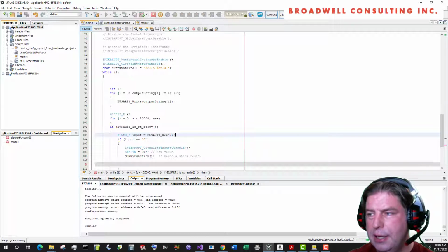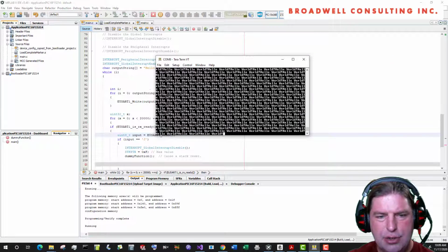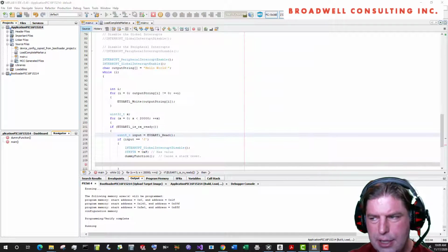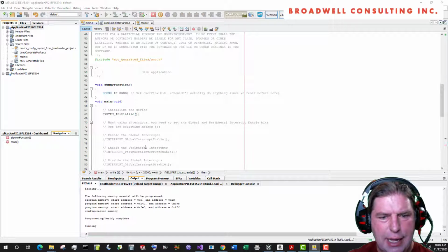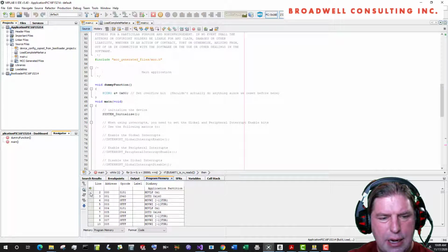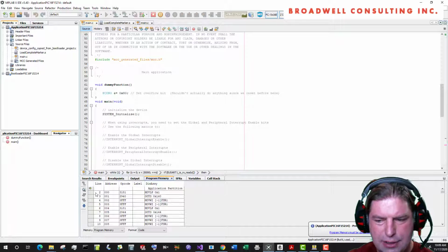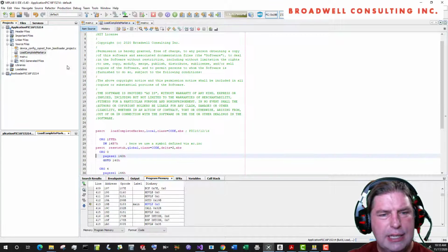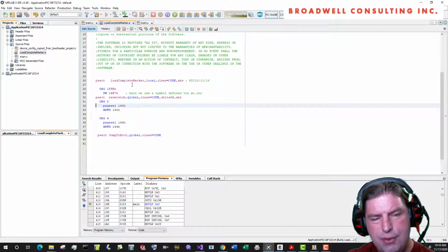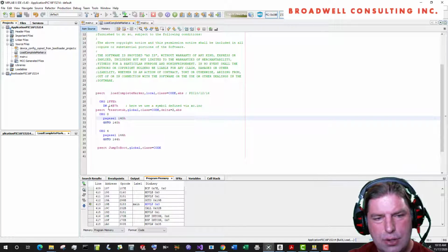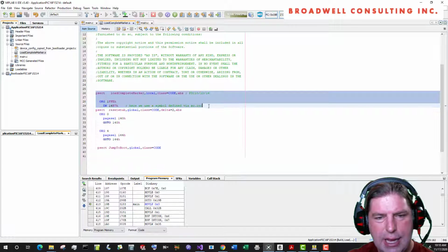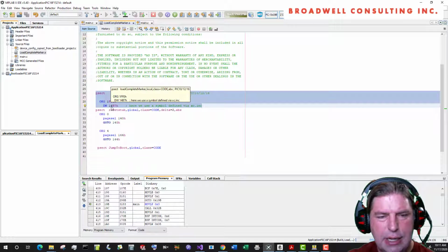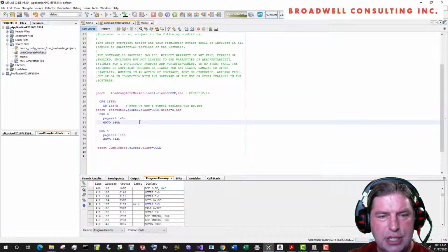Okay, so we were running. And if you look at the serial port that's connected to this, it is dumping out a constant hello world. Let's do a quick reset on this guy, and let's look at our reset vector. If we look in the .s file, there's a few things in here that are important. First, we use a PIC16F15214, an org, and a define word statement that set the magic number that we talked about. This goes all the way at the end of flash.